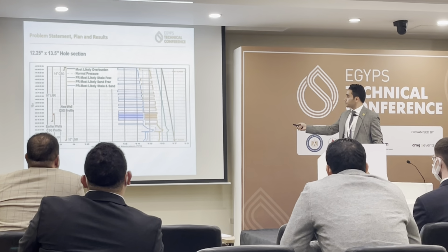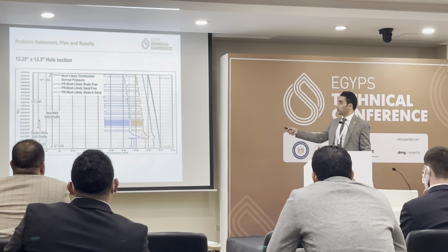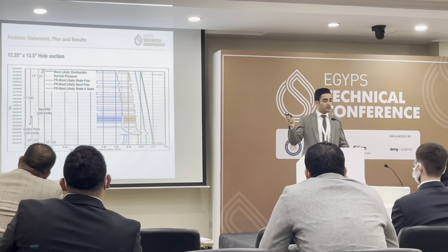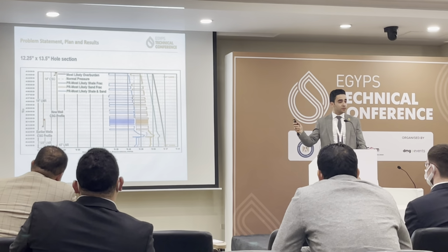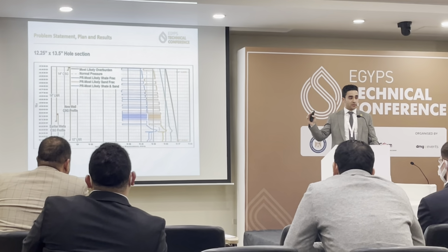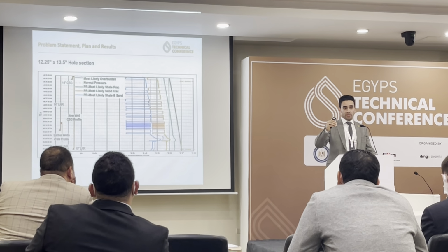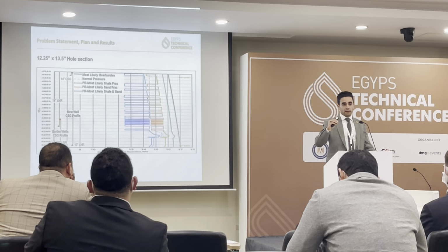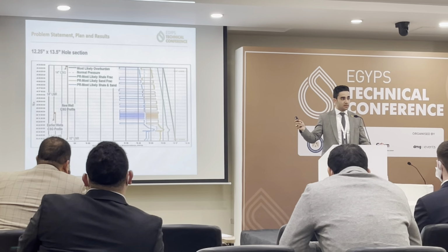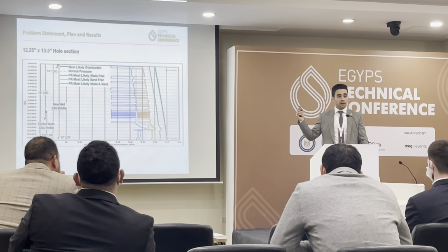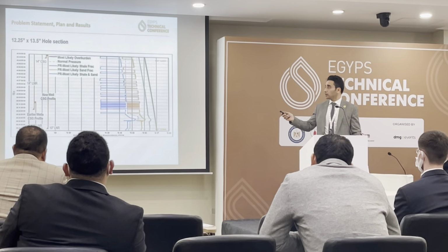And drilling this section was very challenging. We drilled from 4,508 meters to 4,755 meters conventionally, while dynamically stress caging and strengthening the formation while drilling, by loading the active mud system with stress cage materials at a concentration of 19 pounds per barrel.